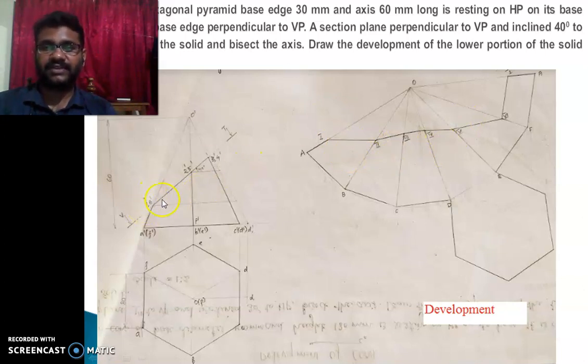What we are going to do is, initially you transfer these points onto the true length line, by drawing a line through the point parallel to XY up to this line and locating a point. Measure the length of this point from O. You measure this line and mark that point on the corresponding edge. That is, if you are transferring the first point onto the true length line D1 dash O dash, you measure the length of this point from O and mark that point on OA, because the first point lies on AO. Similarly this point also will be 1.